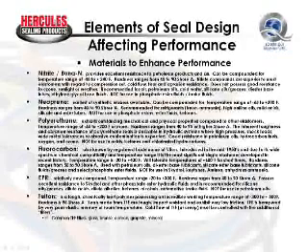They try to control that with the addition of certain types of fillers. Common fillers in Teflon seals are glass, fiberglass elements, bronze elements, carbon, graphite, and mineral. And different fillers will have different characteristics and might be used in different applications.